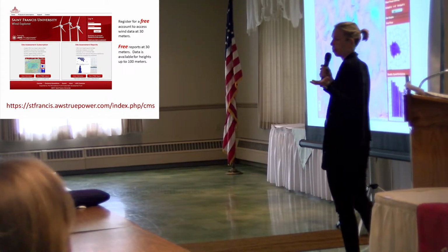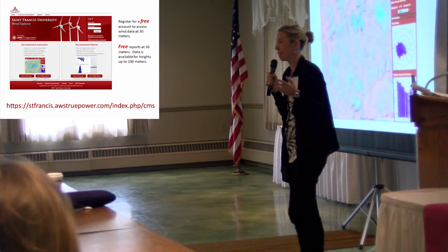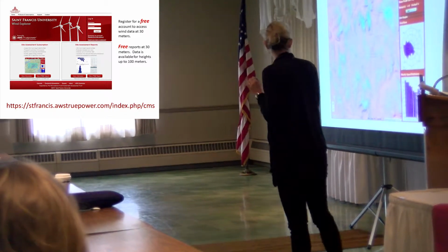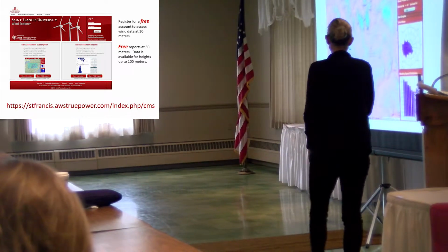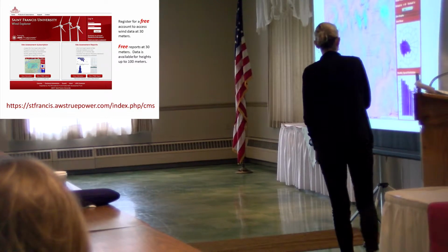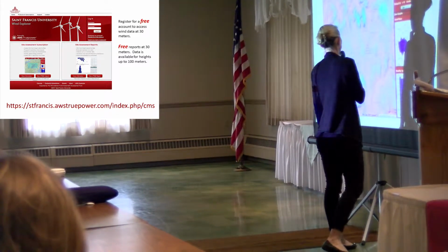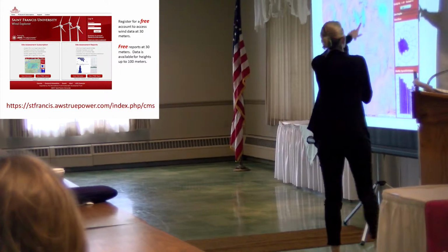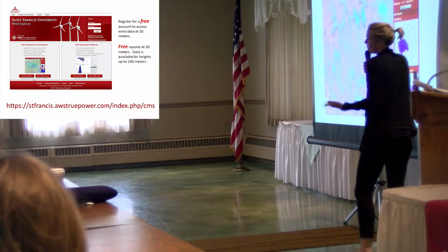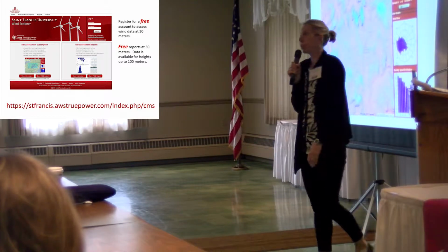And like I said in the previous slide, you need at least 4.5 to even consider a small wind turbine. So maybe this wouldn't be the best location, but if we look around, you can see that some of the higher elevations, some of the ridge tops, are in the 5 meter per second range and start to become feasible in this area.